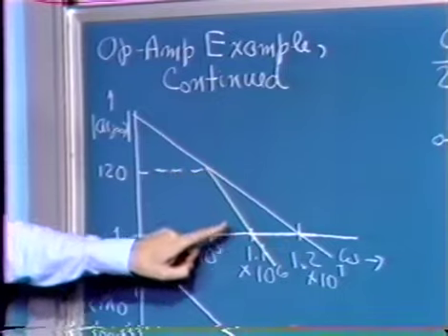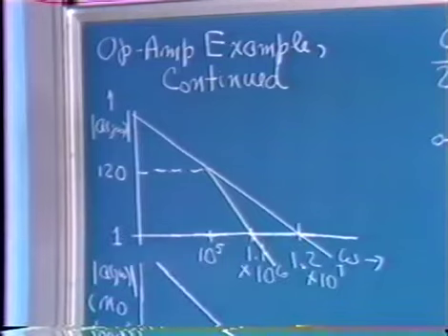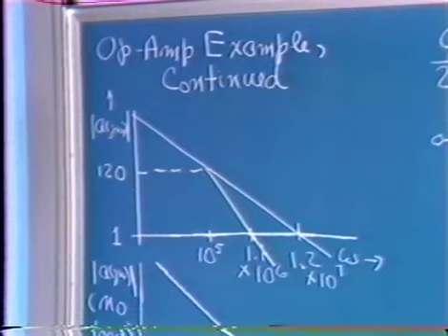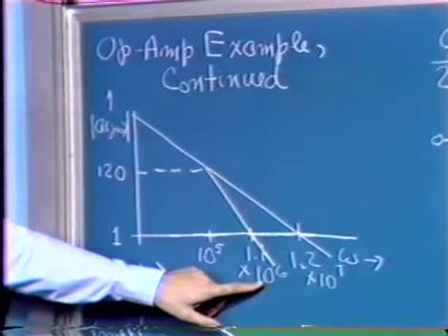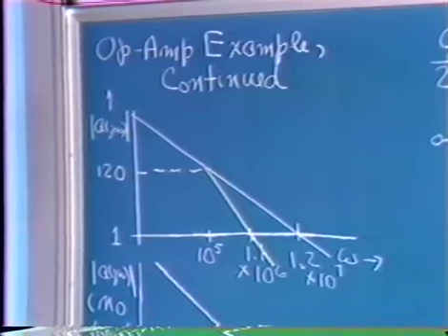We cross over at the geometric mean between this frequency and the original crossover frequency, since we're falling off as 1 over s squared. And so we cross over somewhere on the order of 10 to the 6th radians per second, or maybe a little bit higher than that. And that corresponds to the roughly 200 kilohertz ring frequency that we saw on the oscilloscope trace.